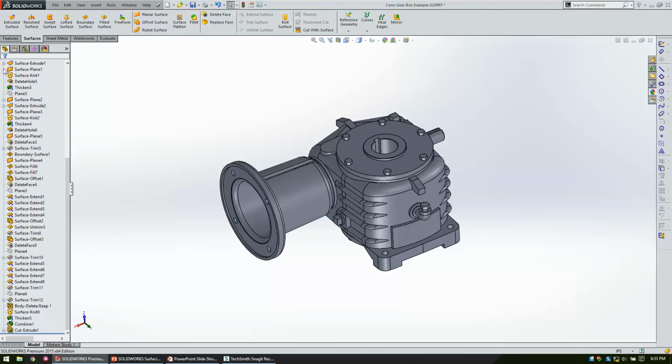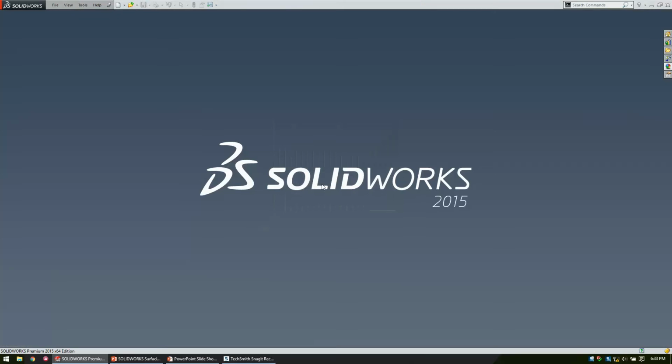If you have really big gaps, like 40 thousandths, I would maybe go back and fix it manually, because some of that automatic gap fill gets really weird. It'll just pull it down and contort your model. But yeah, good point. Thanks for bringing that up. Gap control is very helpful when properly utilized. Any other questions or comments anybody wants to bring up?